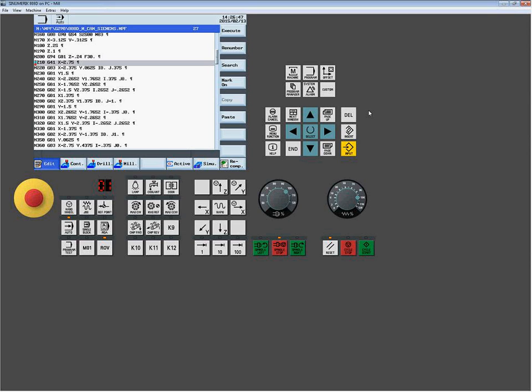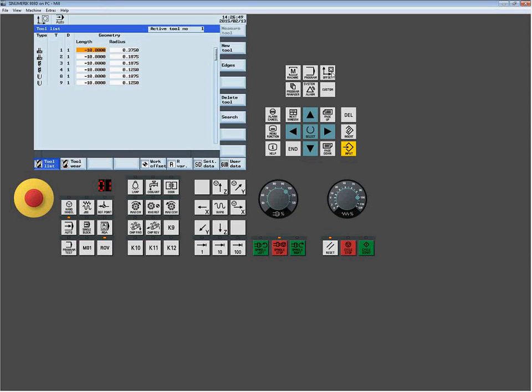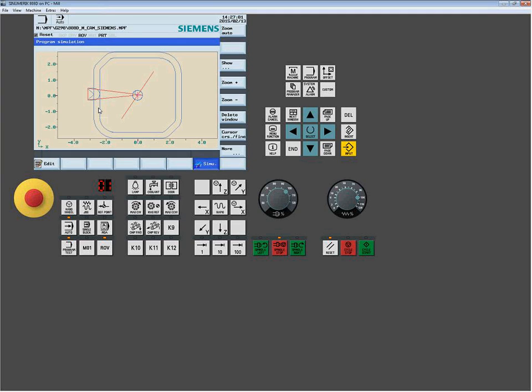But since the 41 is there, I have to set up my tool with a 0 as my radius, and then as I adjust it, I can put maybe a small value here, and then simulate it. I'm going to get a new cutter path just off of that.